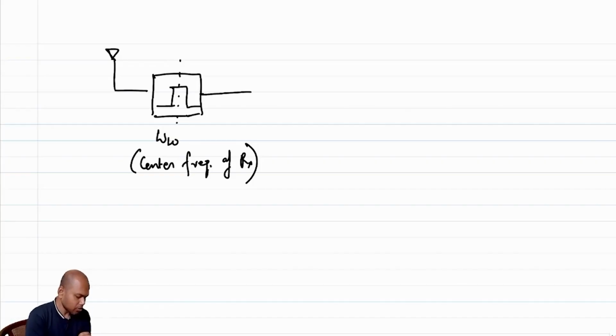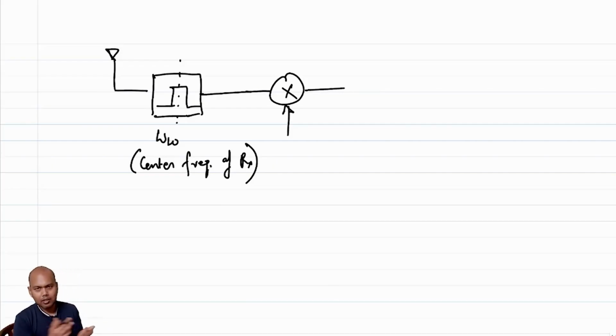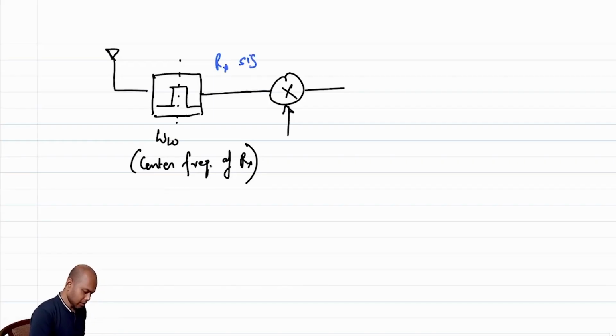Okay. So now you have this, and let's say our mixer can handle minus 10 or minus 20 dBm of transmit power. Let's assume it can handle that, but the intended signal is still very weak. The intended signal is approximately of the order of minus 90 to minus 100 dBm. So your Rx signal is of the order of minus 100 dBm, right?